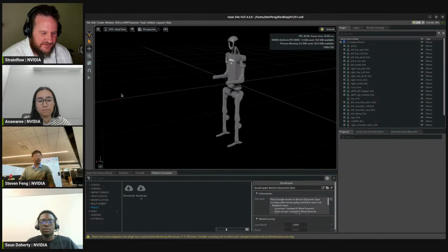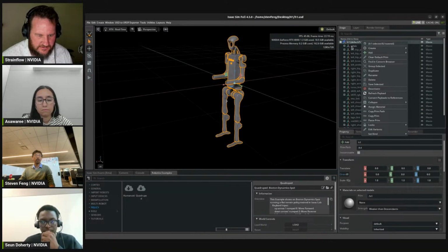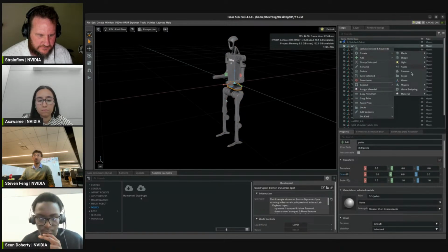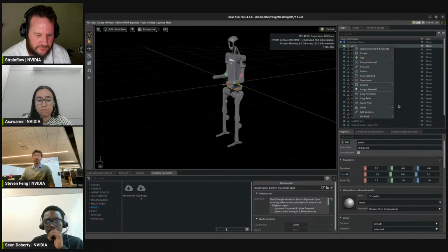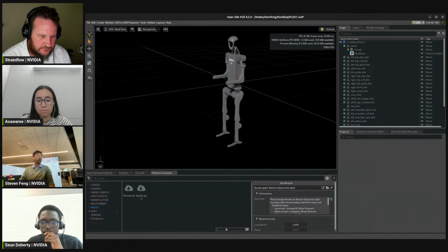So essentially, I'll just explain the concept itself. Let me just add a quick fixed joint to the pelvis so the robot doesn't fall over when we start a simulation. Create physics joint, fixed joint. Okay, so if you start a simulation, you see a robot is like this, but this is not quite matching the default position of what we expect the H1 to be.